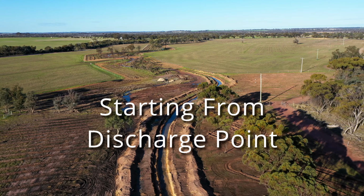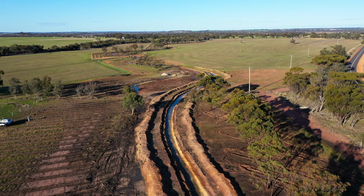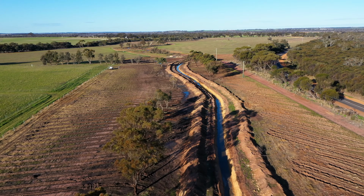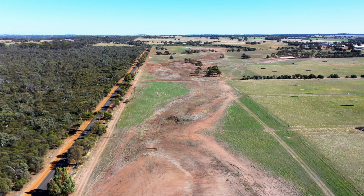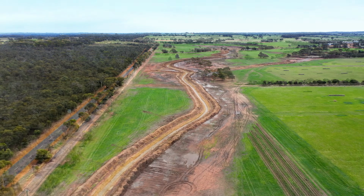As a general rule when constructing groundwater drains, we start at the bottom where the drain is going to discharge, and then we continue upslope from ground level till we reach the nominated depth of the drain. And if the land slope allows, we can then maintain that depth.